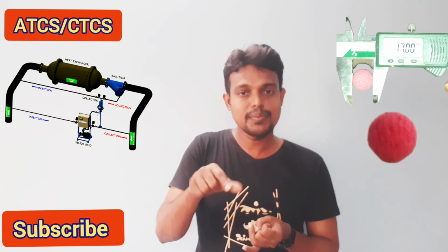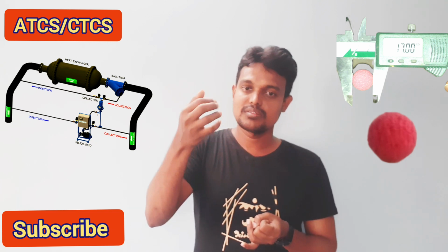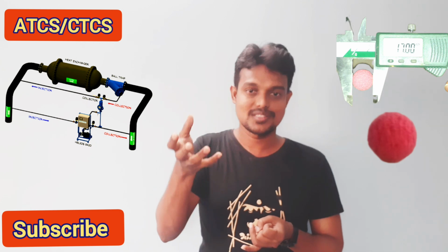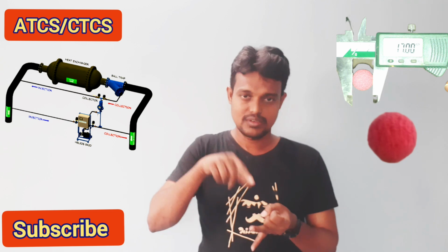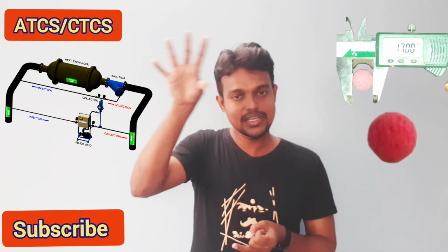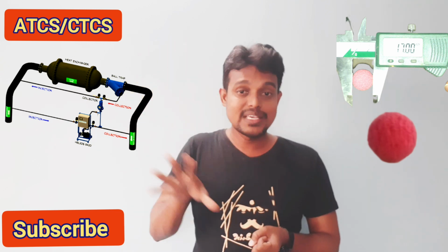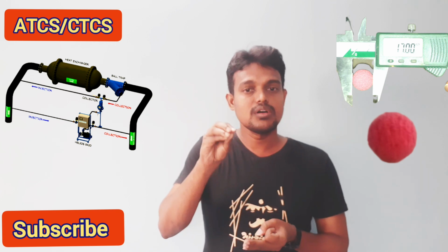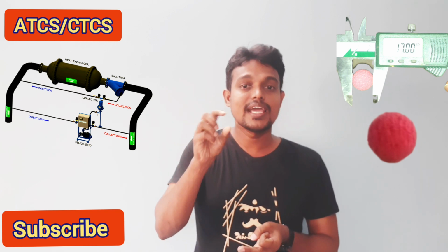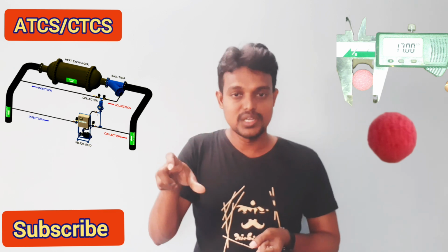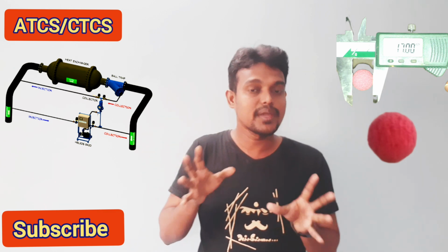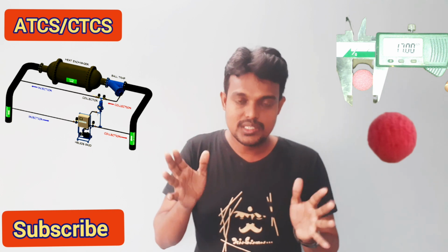In that ball trap we have the strainer, which we call the zero ball strainer. You will also have the entire piping system, and the natural rubber sponge balls in your auto tube cleaning system. These are the main components of the auto tube cleaning system.